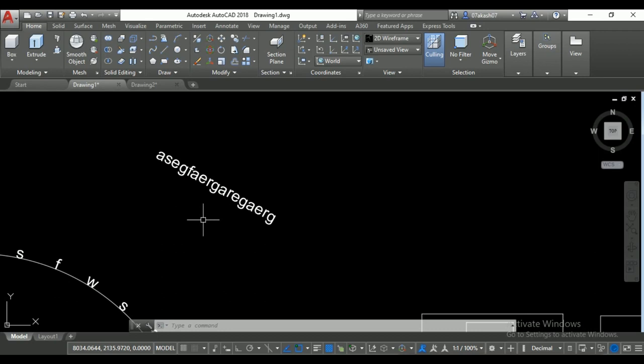So how can you do it? If you use the rotate command, then you need a proper angle for this object. So you will not be able to rotate with the rotate command to a specific horizontal and vertical direction. So we'll use the text orient command, which is helpful for an undefined angle of the text, and it will be converted into completely horizontal or vertical. Okay, let's see how it works.